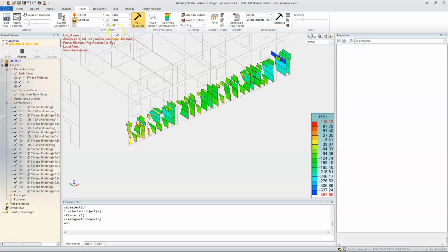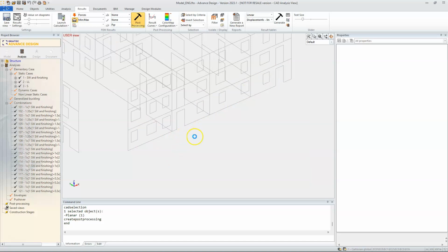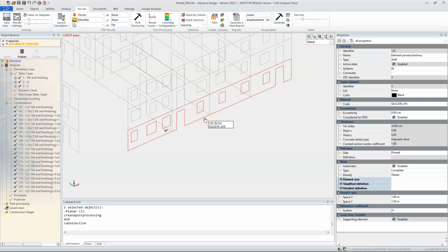So the internal forces right now are the basis of our design. But as I said, the design forces that we will finally use are calculated using the strip method. At this moment, we can't see what will be done because we need to provide some strips. But what's most important is that automatically, by default, the strips are assumed between the openings. So each panel you will have between openings will be calculated on this integrated effort.